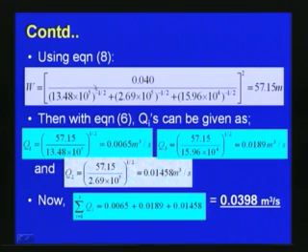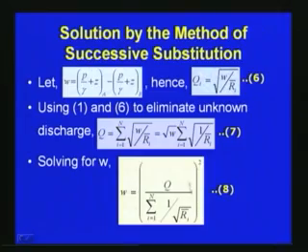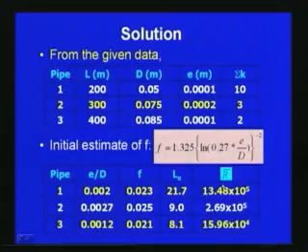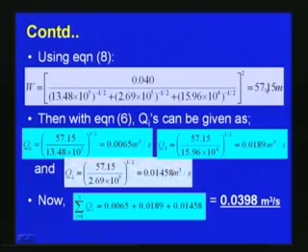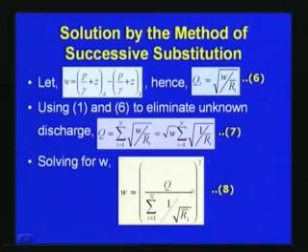Then, using equation 8 as we discussed earlier, we can now find out W. Here Q is known, 0.04, and R bar is already calculated. So, R bar to the power minus half, then sum up and all square. This W is equation number 8. Using it, we get W as 57.15 meter, and then we use equation number 6.